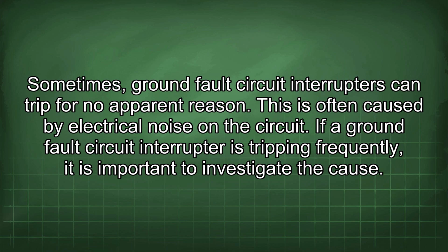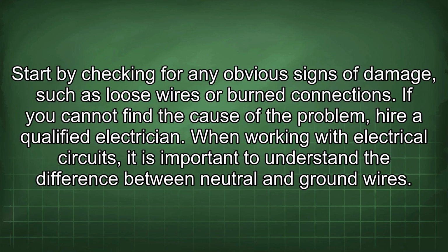If a ground fault circuit interrupter is tripping frequently, it is important to investigate the cause. Start by checking for any obvious signs of damage, such as loose wires or burned connections. If you cannot find the cause of the problem, hire a qualified electrician.